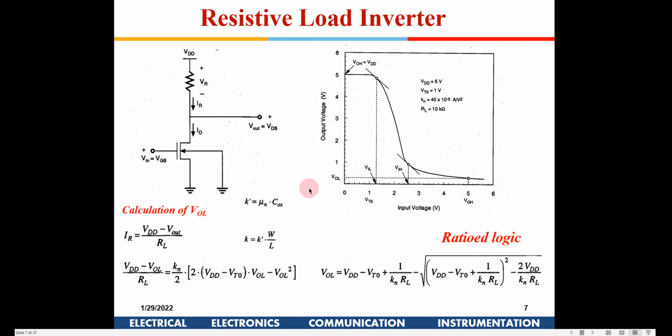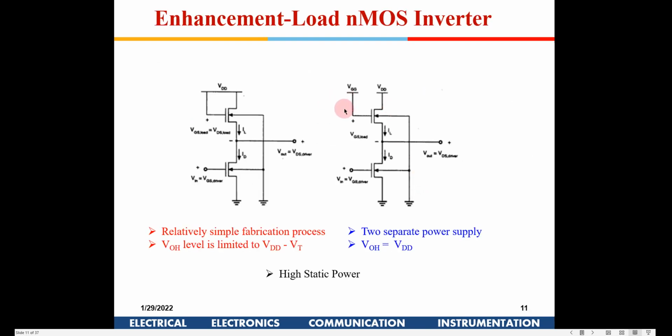Okay. In the second figure, how is VOH equal to VDD? Here now you can give the output voltage out here. What will it be? Vout is equal to VDD minus VTH, right. So in this case, the threshold voltage will be dropped across this, so you can have an increased VDD here, so that you get the desired Vout here. So you are using two different power supplies here. That is the reason we are having these kinds of circuits. Actually we have one logic voltage here and one increased voltage out here, so two separate power supply voltages are required.